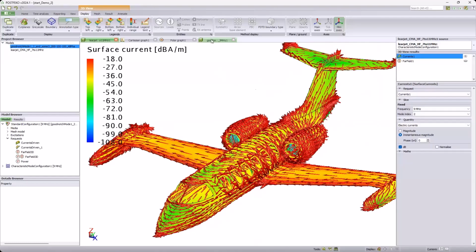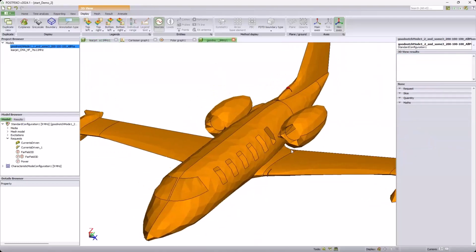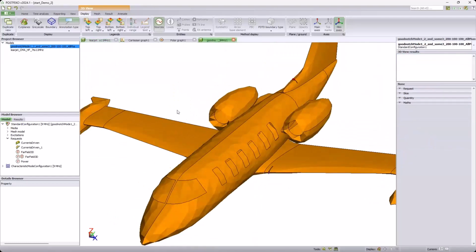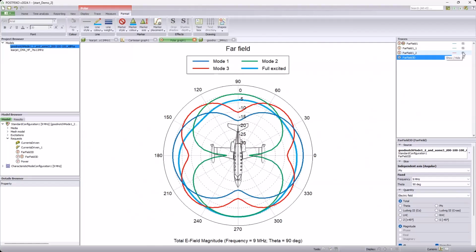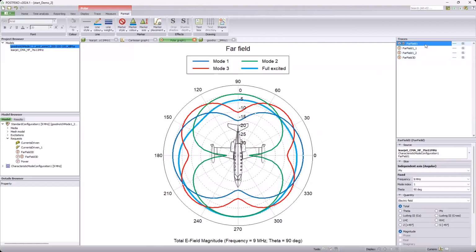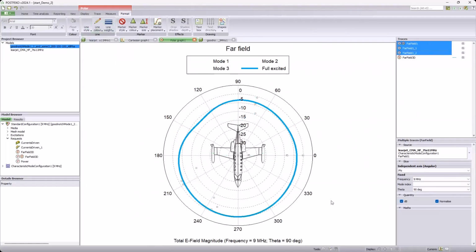And in our example here, we had them 45 degrees out of phase, and I can show you the end result of that is this blue trace. So it should be that by combining those 3 antennas and phasing them to excite a combination of the 3 modes, we are able to achieve a radiation pattern that's got a strong radiation in the forward direction.